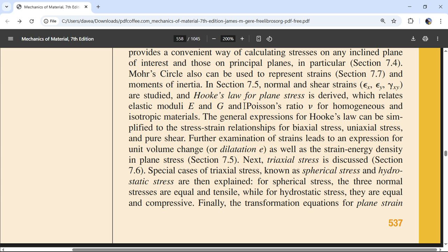Cool. All right, and so we have Poisson's ratio, which is if you pull on something, it's going to shrink. If you pull on it in tension in this direction, it's going to shrink in this y direction and the z direction, and it's going to change in volume in those directions. But it's actually going to lengthen in the x direction more than it's going to shrink proportionally in the other two directions. So still, if you're pulling on something, it's going to have a net increase in volume. All right, so that's Poisson's ratio.